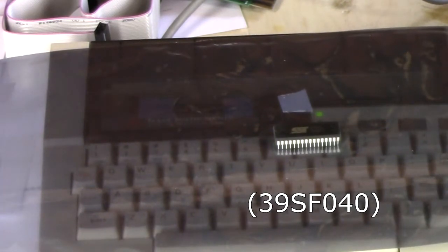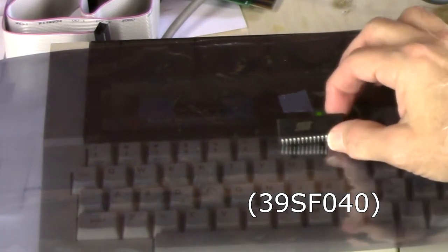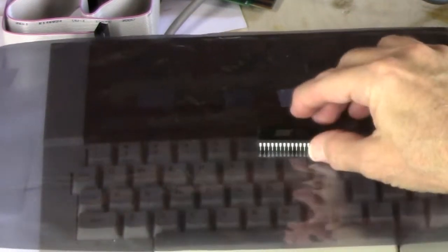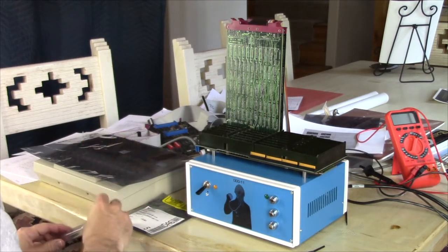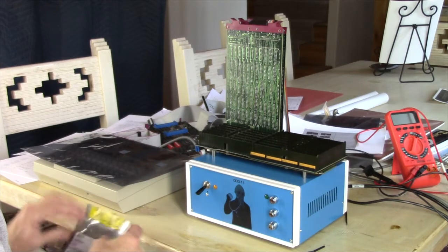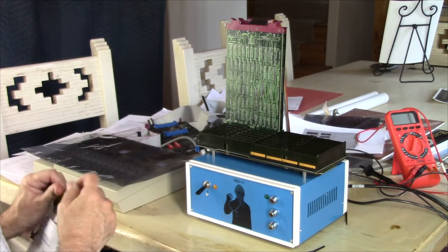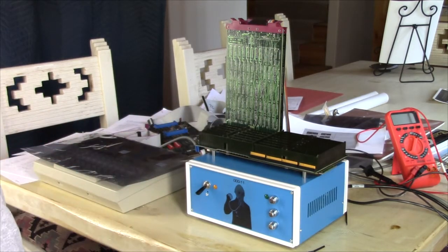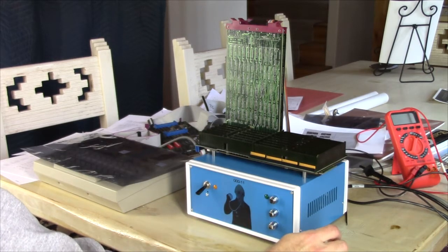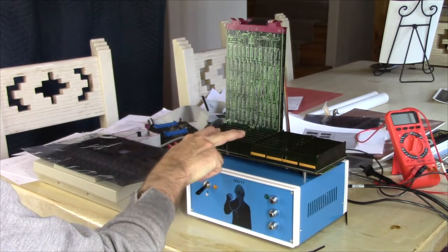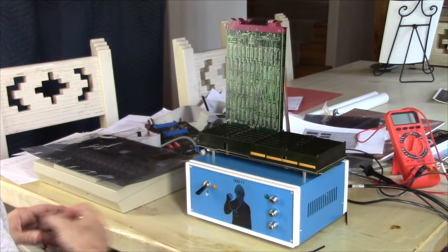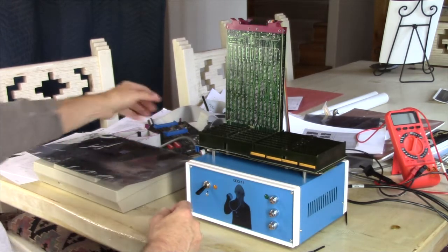These are 512K by 8 parallel flash memory. Now, how do we get the computer to access that? Well, we could do a full custom board. That gets difficult because some of the driver chips that DEC used for the Q-bus are really not available, so you have to use substitutions, things like that. And that would be a lot of work.